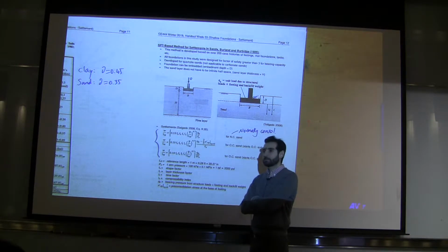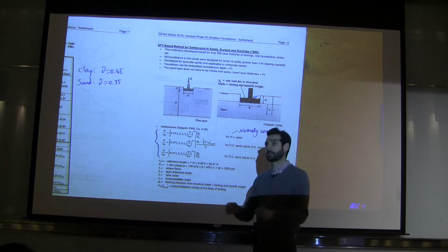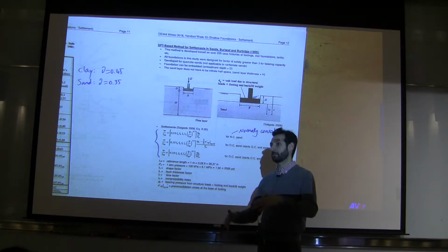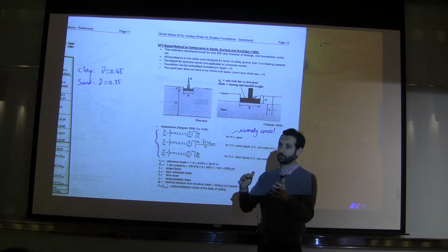No, it doesn't change the sigma prime Vp. Sigma prime Vp is before you excavate to build the foundation. So the backfill was already there. You excavate it, so then the stress goes down, and then you build the foundation, you put the concrete on, you put the structural load on, and you may or may not add the backfill on.